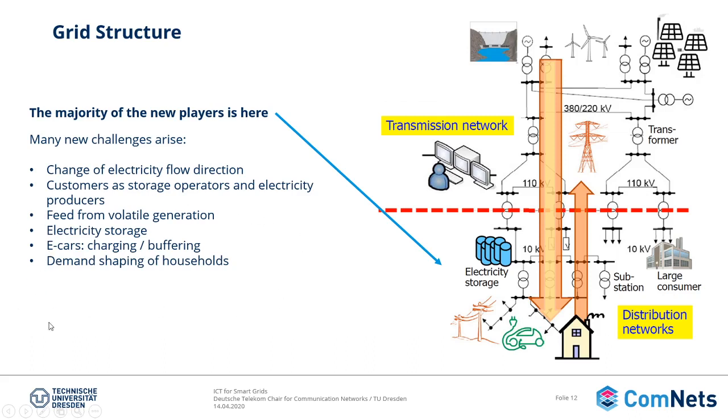And that brings us to the next point of demand shaping. Demand shaping is the scheduling of electrical equipment in order to keep a constant power demand profile, and not a hugely changing power demand profile full of spikes. There are some applications, and as I said, some startups that provide platforms that actually do this for you. You hook up all your electrical equipment to smart plugs, and the platform turns on the electrical equipment in order to shape the power demand.